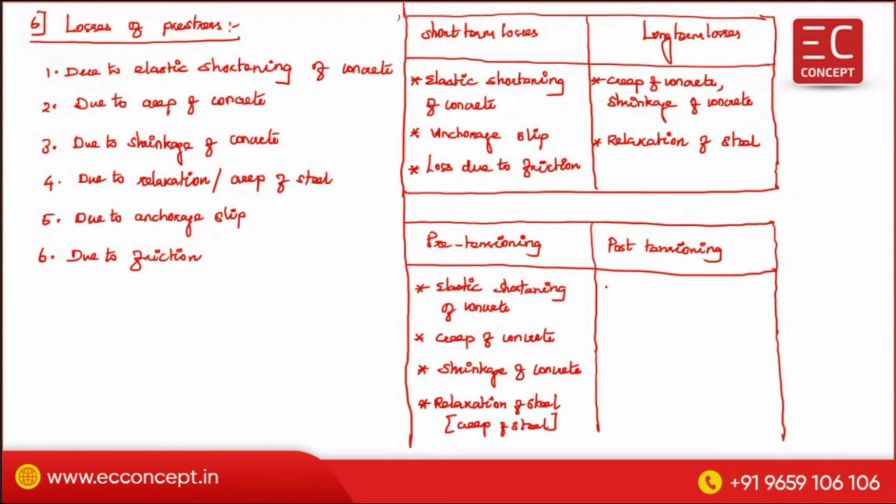Then post-tensioning, that is, loss due to elastic shortening of concrete is not present, in case of, that word is important, in case of simultaneous tensioning.